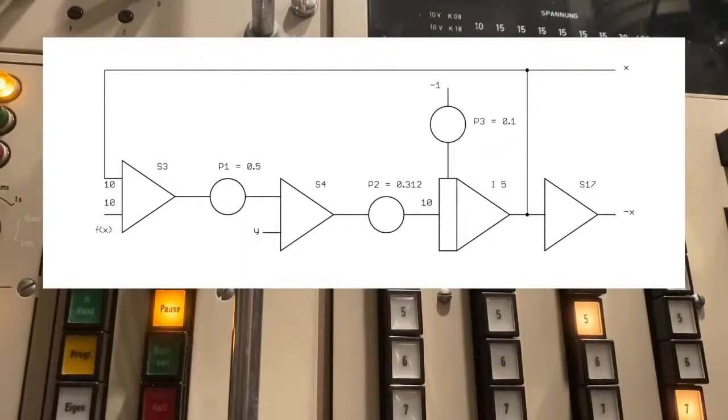Without the ability of introducing any initial condition, our analog computer setup would just sit there and do nothing, since all integrators would start with a value of 0. But to actually start a computation, you need at least one value which introduces something into the analog computer setup so that it can, for example, oscillate in the case of our Chua oscillator.